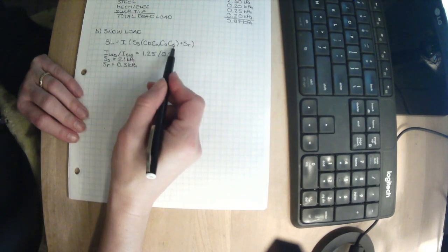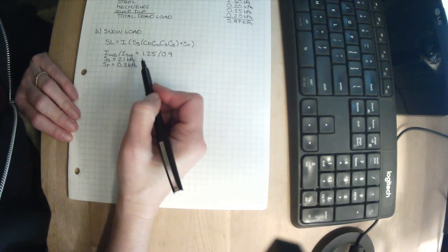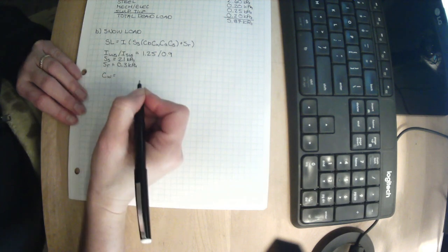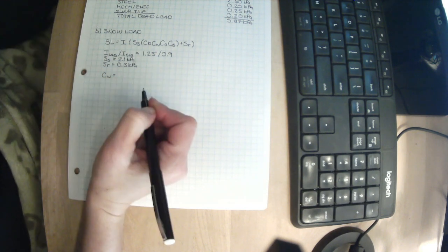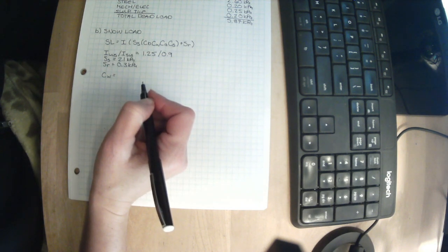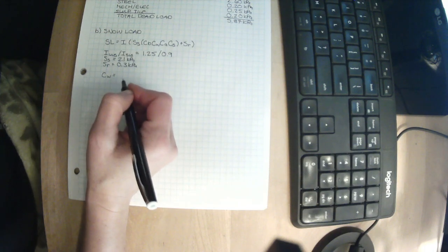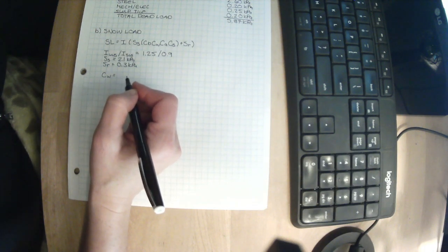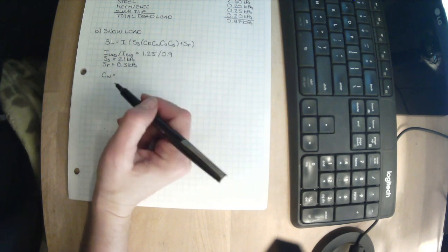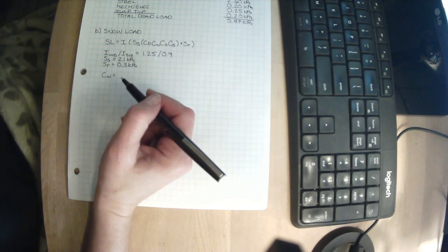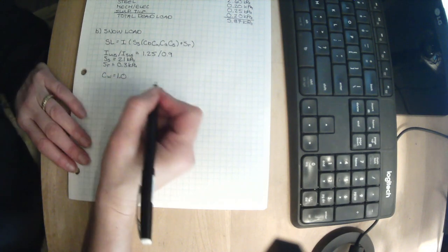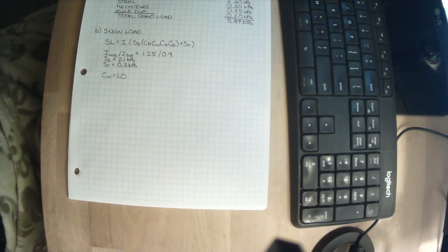The other things we need to figure out are our factors here. Now, CW is about our wind scour, essentially. Now, we said that there are no buildings taller than it, but that doesn't mean there's not buildings around it. To be able to wind scour, you need no obstacles around your building for something like a kilometer away. It's almost impossible to have anything but one. I've rarely used less than one for that.